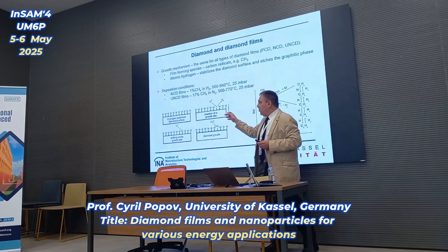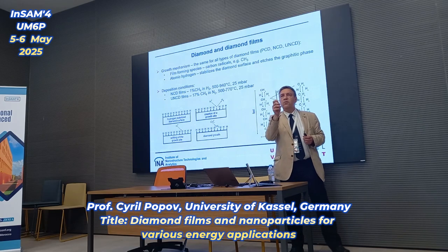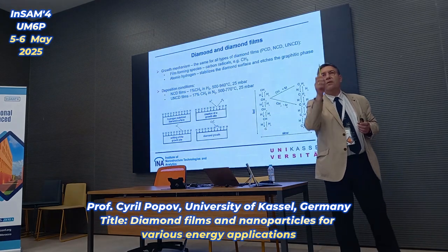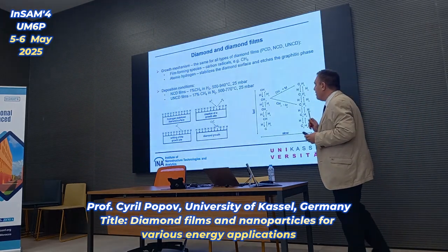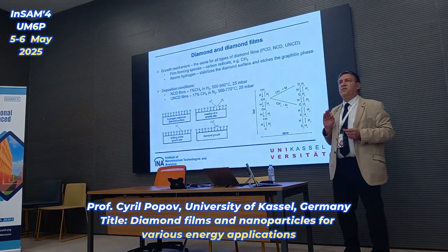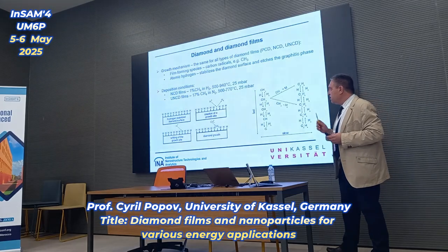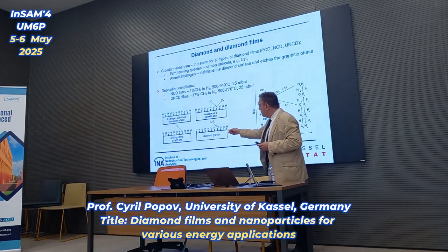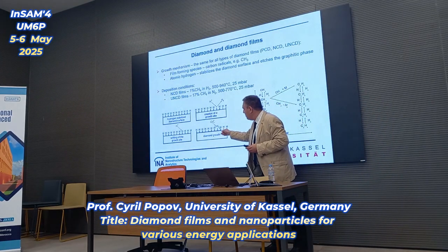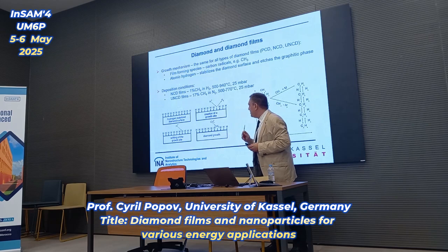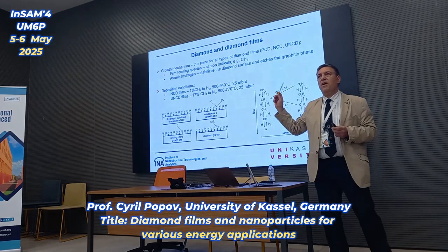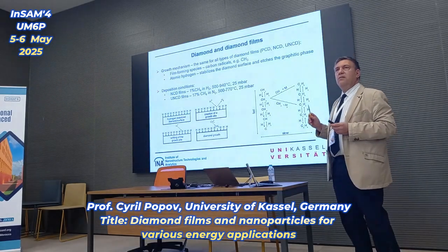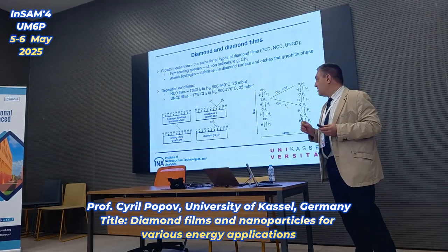When we have a carbon bond pointing to the surface that is not saturated, a hydrogen radical comes and stabilizes the surface. In addition, it can make a place free where the methyl radical is incorporated. So this is the growth phase. This is the first role of hydrogen, stabilizing the growing, but also the final diamond surface.